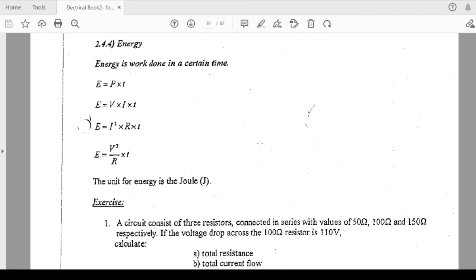So if I give you 5 days, you need to change 5 days into seconds. It's 5 days times 24 hours times 3600, because each day there's 24 hours. That's going to be a long calculation. Yes, usually they ask like that. And then your power must be in watts if we want our answer to be in joules. But if they say what is the energy in kilowatt hours, then leave your power in kilowatts and the time in hours.